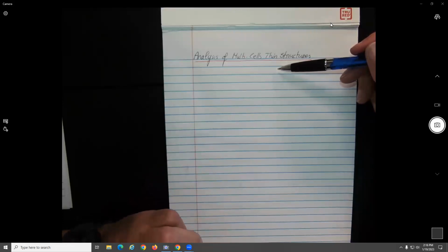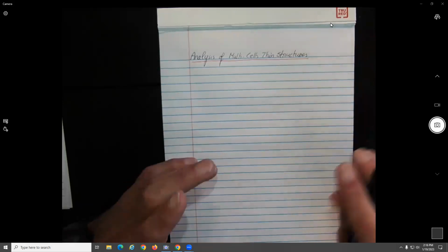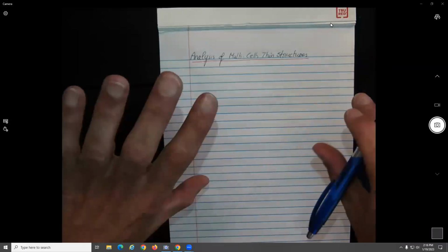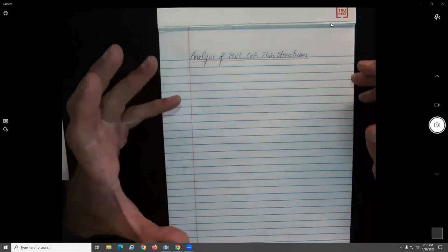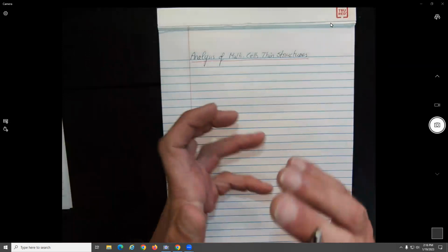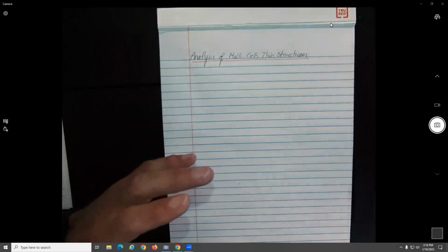It's bending. So basically, all the equations you derived when you were doing solid mechanics had that sentence, long and slender members. The main assumption, because you assume they are long so they can bend. So if you're going to break it, you're going to break it by bending, no? If you have something that is very short and thin, how are you going to break it? Probably going to try to twist it. That will be shear, no? But most of the structures, buildings, wings, fuselage, are long and slender in general, no? So thin, long, slender basically implies that the main load is going to be bending, instead of shear. All right.